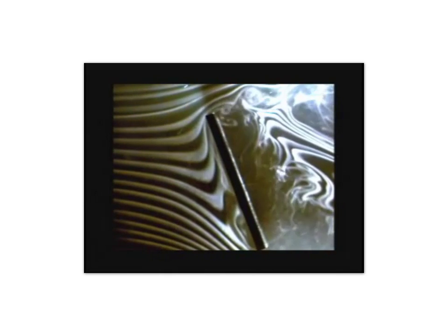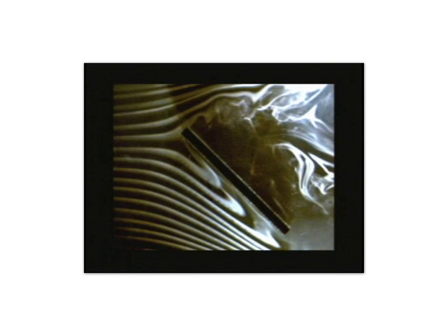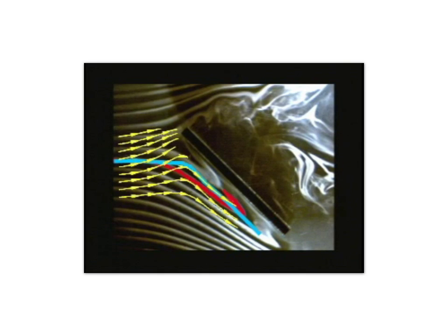A timeline is rather different. It is a line of fluid particles across the flow at a given instant, and it reveals the velocity profile. In unsteady flows, streamlines, streak lines, and path lines can be quite different. Here, the unsteady flow over a rotating plate is shown. When the flow is observed at an instant when the plate angle is the same as in the previous steady flow, we can see that all 3 lines differ. The streak lines and path lines, which developed over a time history while the plate was rotating, differ from the instantaneous streamlines.